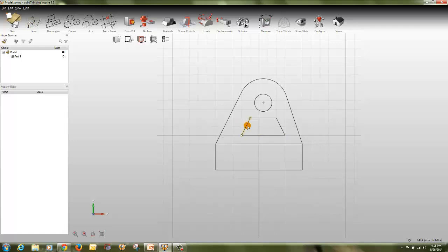So now if you select these two and activate the parallel constraints, so this will be parallel, as you can see. Similarly, these two, if you want it parallel, so this will become parallel also. It automatically shifts. You can see that. So these are the parallels. It's fixed to the parallel.